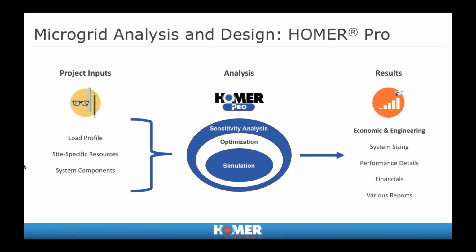the grid, we want to see how a system would perform if you were to add solar to this, or if you added solar plus storage, or solar plus storage plus wind. We want to simulate hour by hour through each time step, or you can actually choose a different time step if you'd like, with real world conditions, switching how we use energy from each energy source, whether that be the wind or solar or grid. And we have a controller that would maybe charge your battery from the grid or generator. This switching is known as dispatch, and this is how we step through our simulation.